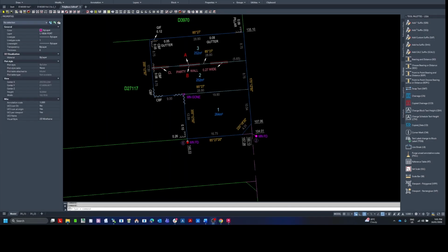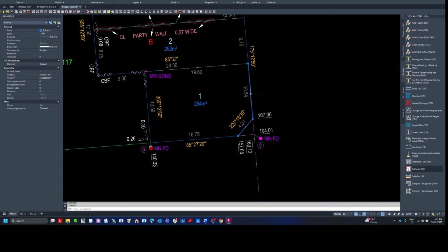Drafting tip number 5, polylines and natural boundaries. Avoid polylines for parcel boundaries when distance and bearing labels exist. So for a line like this, which is a polyline in your DWG, which has a distance label, has a bearing label, and in this case has a chainage label, our data processing will struggle to be able to validate the distances against those lines as they are connected to each other.